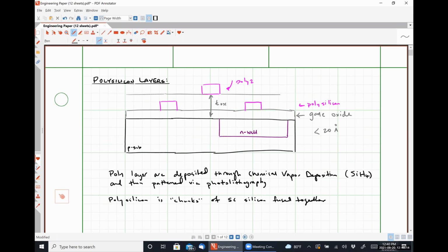Do you think that's going to make it easier or harder to turn the transistor on? Harder, significantly harder. So you effectively have two different voltages that you can use to turn on transistors in a 2 polysilicon process, right? One's going to be a small voltage, typically on the order of 0.6 to 0.7 volts for the poly that's very, very physically close to the substrate. And it could be as high as 1.5 to 2 volts for the poly that's further away because of that very, very large oxide thickness. Okay, so it gives you a second transistor technology to use within the same process node.